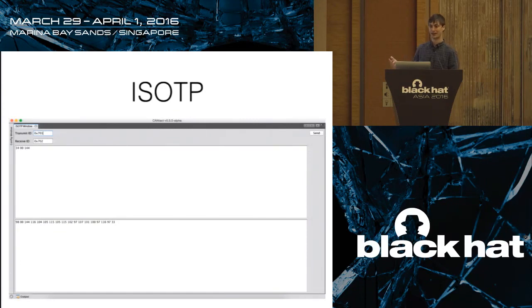Now, what the ISO has standardized is this ISOTP, which is ISO Transfer Protocol. It's also called CAN-TP. It's sort of an interchangeable name. And it's just a standard for saying, I have up to 4,095 bytes I would like to send, and how do I get them into 8-byte CAN frames? It uses some kind of metadata on the frames in order to say this is the first frame and we're going to send you this many, and send that payload, and there's a serial number counter to make sure you're not dropping packets, and it does all that at a lower level, but it's really useful to be able to do something where you just type in what bytes you would like to send that's longer than 8 bytes, and it sends it.